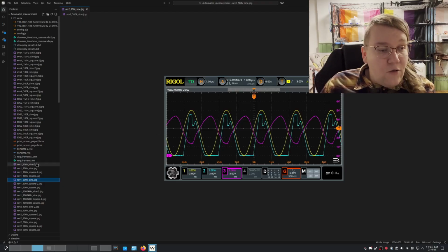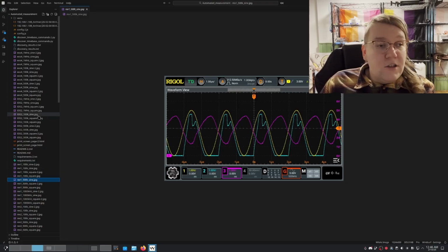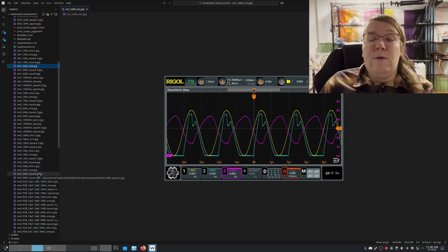So I just run a command instead of having to measure 10 different settings and manually entering all those, which has significantly sped up development, and I can highly recommend this. I would always go for network connected equipment when you can, because it's so much easier to then connect those for automated testing or synchronize between multiple devices. And a simple Python script can control most devices relatively easily.